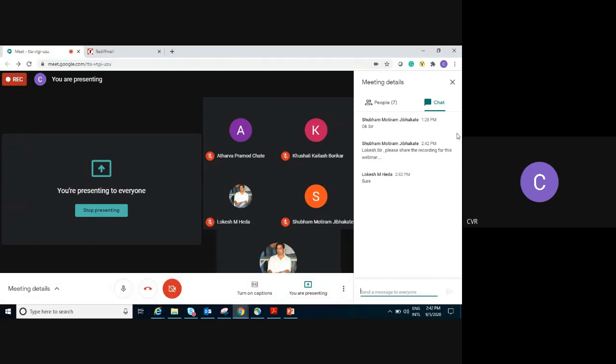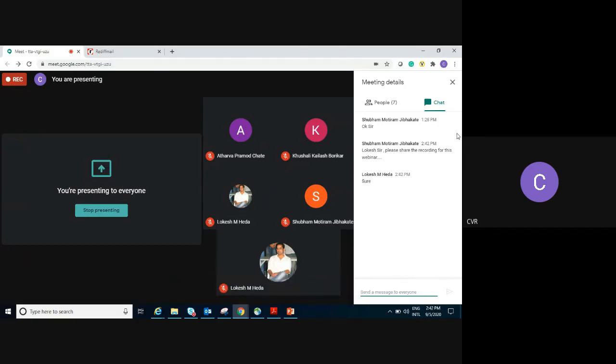The second thing is that when you are selecting the processor, you need to always consider whether the processor has low power consumption, and also you need to look into the operating systems, because this is connected with each other. Whichever operating system you are choosing should support different kinds of wireless communication technologies like Bluetooth, Zigbee and Wi-Fi, and those again have to support different types of communication protocols. And then the IoT protocols and the other things are all linked to each other. So these are the things you need to consider.